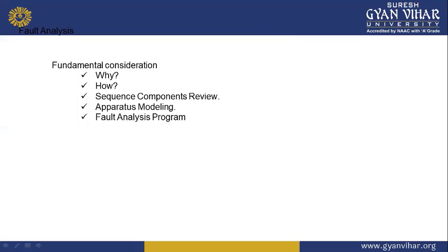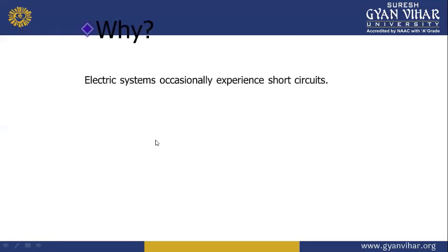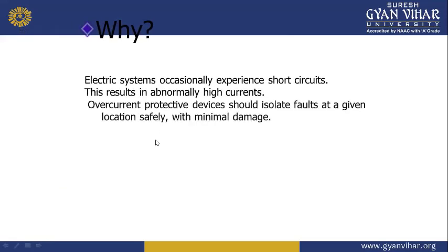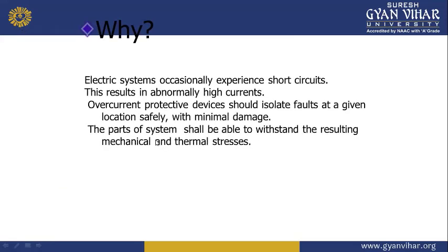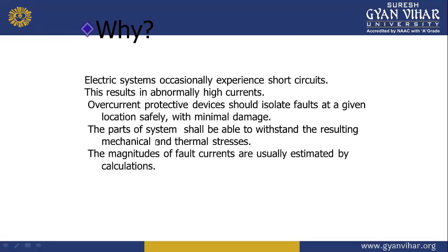The symmetrical fault analysis is of course simpler to carry out. It is important to note that the symmetrical fault may be a solid three-phase short circuit or it may involve arc impedance.